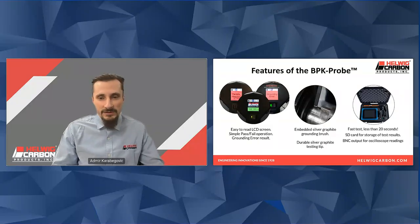And it's fairly easy to use. You touch the BPK probe to the shaft, hit the rocker switch, and within 10 to 20 seconds, you will get a result. Now you can also pair that with an oscilloscope. So we provide an oscilloscope with our BPK probe, or you can use any third-party oscilloscope, and you can see in real time what's happening on that shaft.